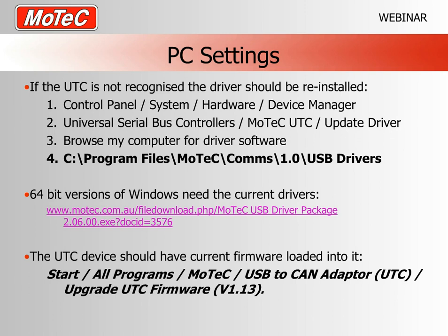That program shows everything that is the hardware on your laptop or on your PC. And if there is a clash with your UTC and the USB driver is not working, normally you will see a yellow question mark next to the UTC. In some cases, it won't appear in the correct tree position in your Device Manager, and in that case it may appear just as a listing of an unknown device.